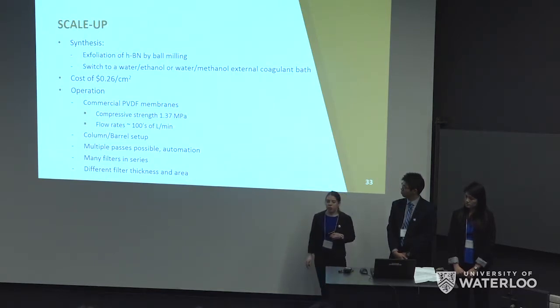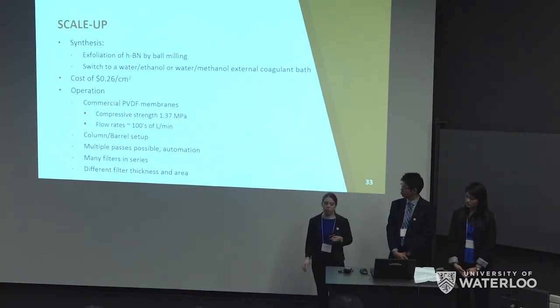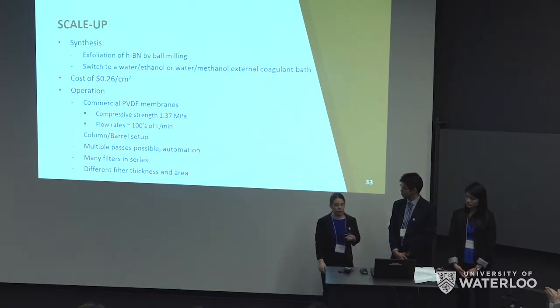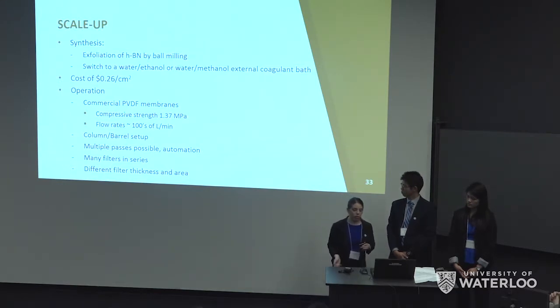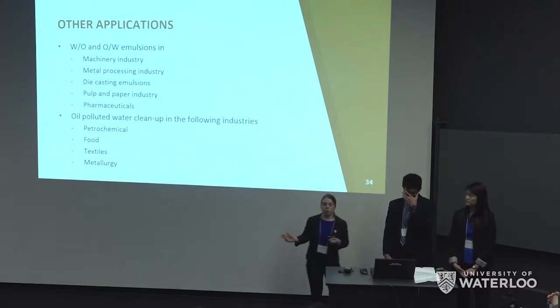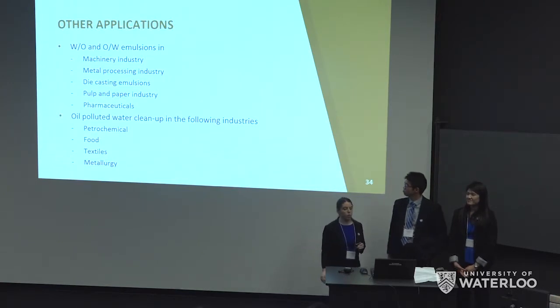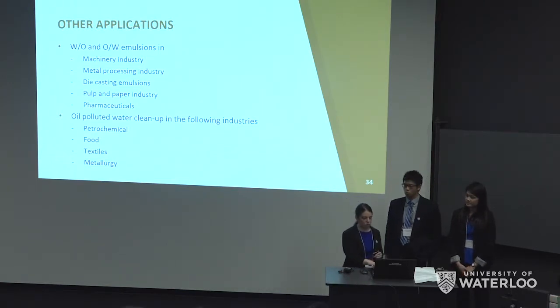And in terms of operation, compared to commercial PVDF membranes, ours is actually much stronger. Those have about 1.4 MPa, ours is about 2.4. We would have to scale up the flow rate, of course, consider multiple passes, and the effect of different filter thickness and area. So these emulsions are found in multiple industries, as you can see here, and this may be extended for oil polluted water cleanup as well.